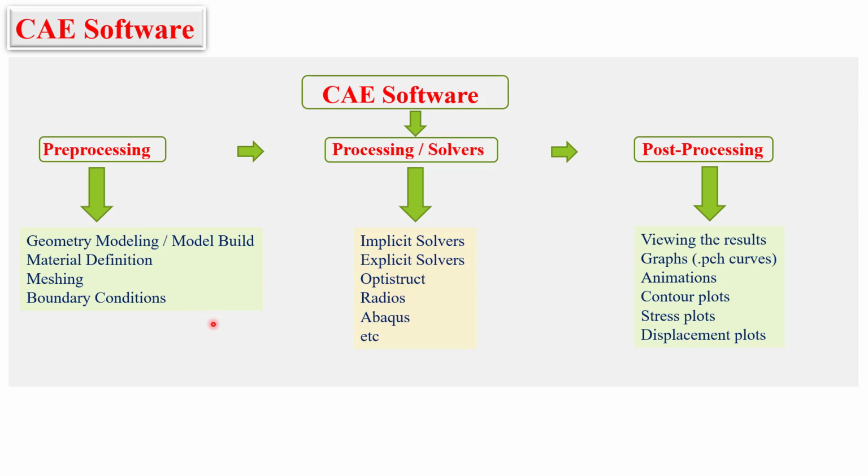You do everything and define the NAS or FEM files and just load it here, and they will solve the results, and then they will give it for the post-processing. As I told, some standalone softwares are there. Only the basic analysis, simple analysis you can do and visualize, but when it comes to complex models we need the independent tools where we are able to view the results in the form of stress plots, displacement plots, contour plots, animation, some of the PCH curves and all. Everything we can do in the post-processing tools.